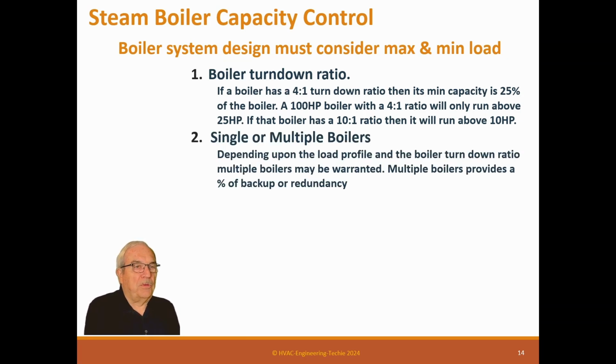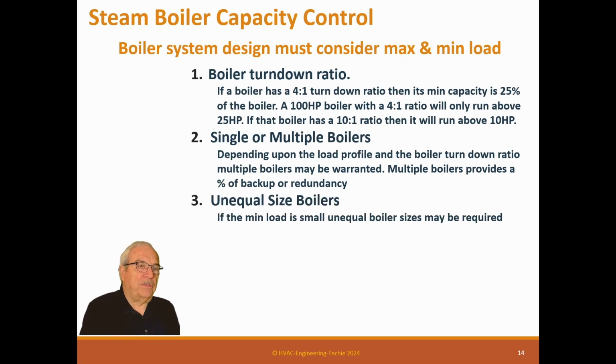Single or multiple boilers may be required depending upon the load profile. Given the boiler turn down ratios, multiple boilers may be warranted. Multiple boilers provide a percent of redundancy, or backup. Unequal size boilers: if the minimal load is small, unequal boiler sizes may be required.